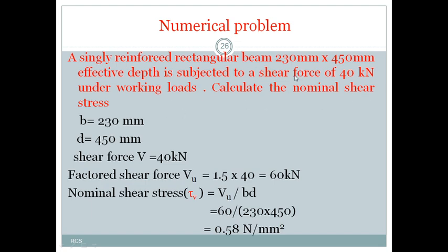Here the shear force is given under working load, but we have to calculate the nominal shear stress corresponding to the factored shear force, which is the design shear force. The design shear force can be calculated by multiplying with a suitable factor of safety.